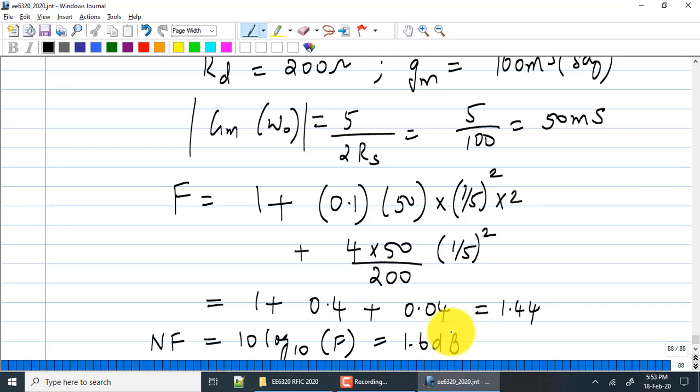Automatically, if you cut down CGS, you can do it in 2 ways. One way to do it is to cut down CGS and keep omega T constant. If you were to do that, the value of LS will remain constant, the value of LG will increase. Does that make sense? I can cut CGS but decrease current also such that omega T stays constant. I only have CGS scaling. If CGS scales, LG has to increase.